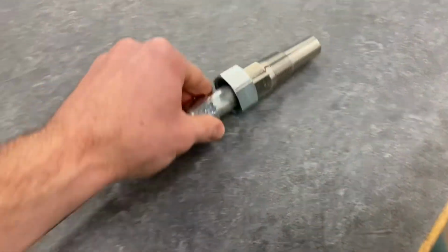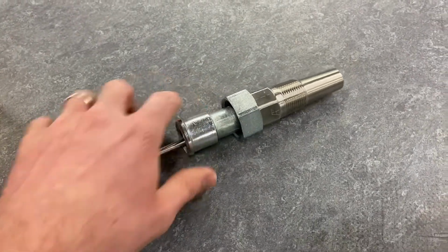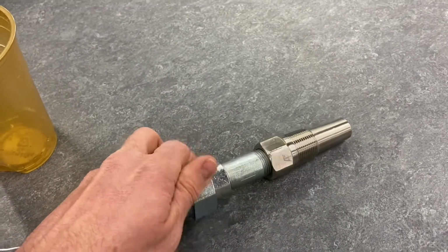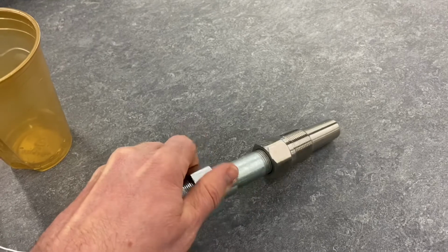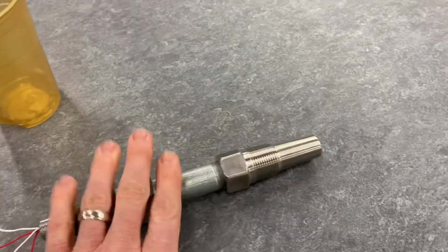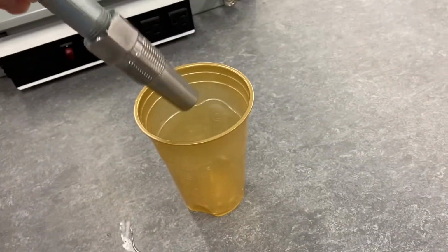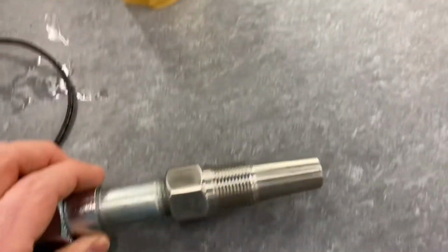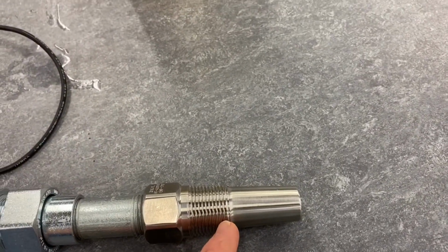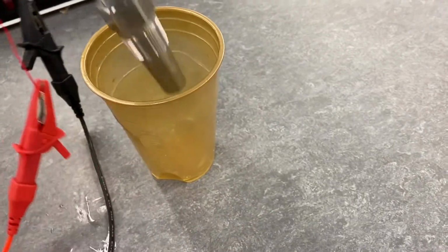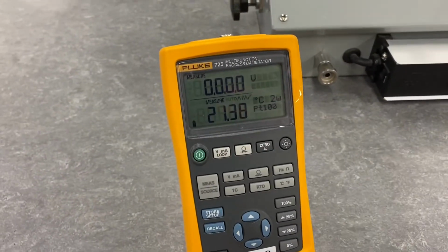And then we're going to warm this back up, and then we're going to install our thermowell on the RTD, thread this on, leave it set up in the 2-wire configuration, and then make sure that everything's at room temperature here and that we're reading stable right here. And now we're going to submerge this whole assembly, and we need to go at least to the threads here, right? So might as well go right up to the top here, submerge it in the water, and agitate it, and record the temperature on our Fluke here every few seconds until it reaches 0 degrees C.